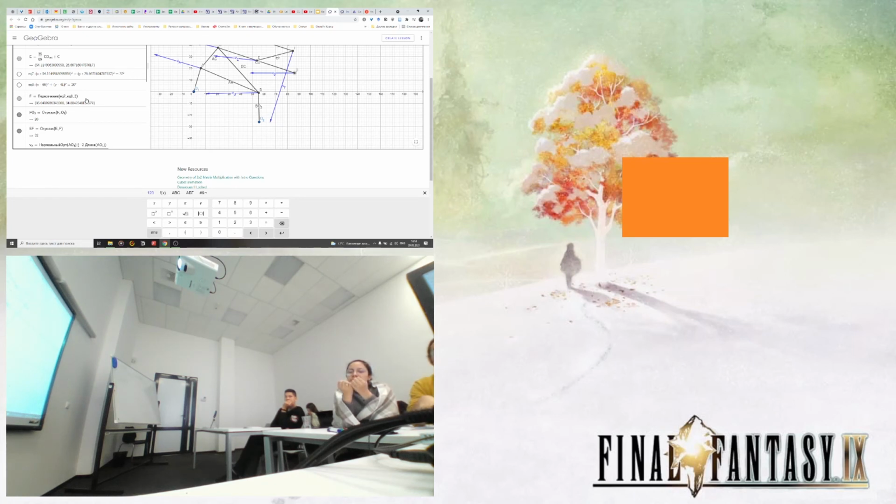In SolidWorks you're not writing equations itself. Yeah, but you can set the angle, and then you will get positions, velocities, accelerations, if you're doing it in a fully parametric way. But you don't want to do it in a fully parametric way, am I right? Yes, you can. You also can make it in, for instance, NX, or in Fusion, SolidWorks probably. You can make fully parametric models, but you're not writing equations. You're choosing a circle, and after this you make constraints, and it finds your intersection. In this case, you find the intersection using math.